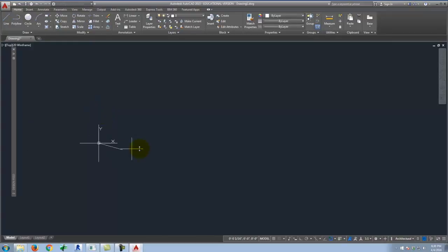So you see a little graphic here that are x and y, and my coordinate starts right there. Okay? From here, I'm going to type in a next coordinate. And in this sense, I'm starting at point 0, 0, and I want a line that goes up the y-axis 24 feet.